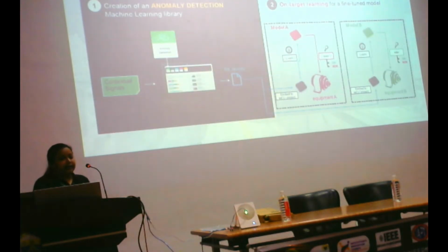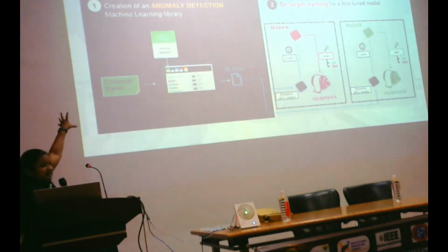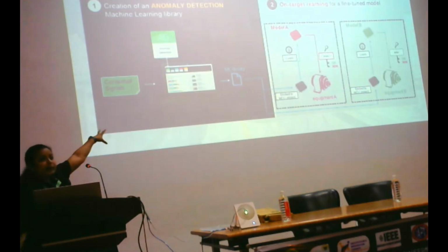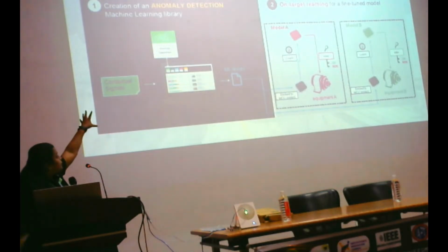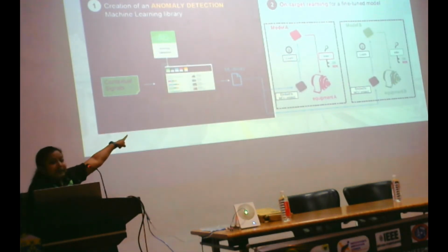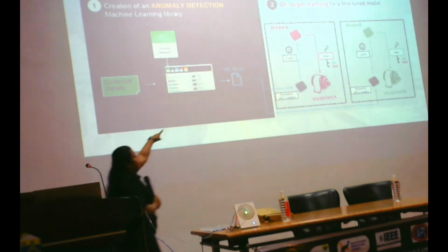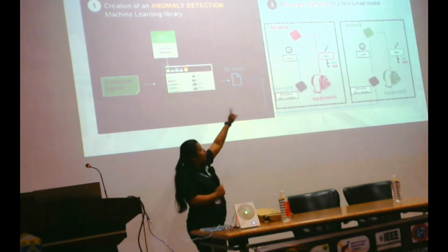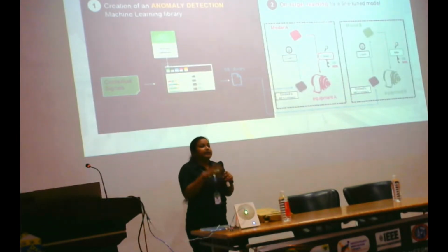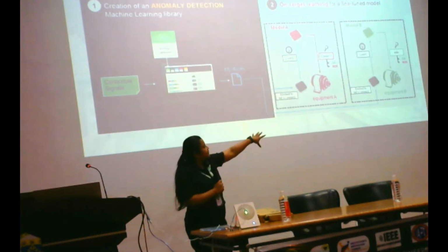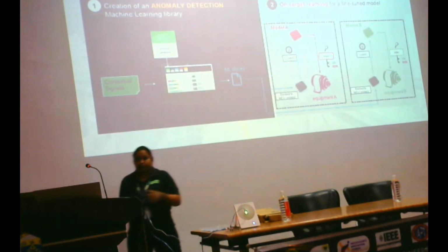Here, talking about the anomaly workflow, on the PC side, we will open the NanoEdge AI software, collect the data, build the model, and get the ML library. Then on the MCU part, we will dump that library, like we'll code it and dump it. That means it gives the normal or abnormal output.